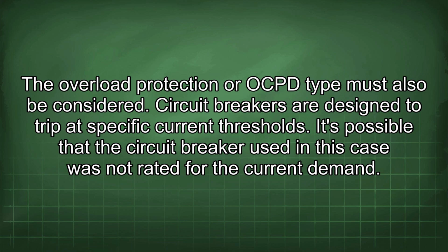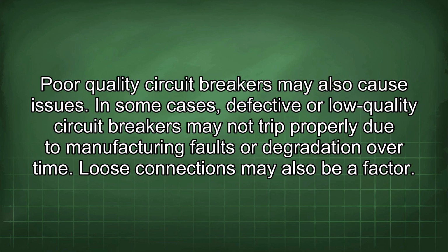Circuit breakers are designed to trip at specific current thresholds. It's possible that the circuit breaker used in this case was not rated for the current demand. Poor quality circuit breakers may also cause issues. In some cases, defective or low-quality circuit breakers may not trip properly due to manufacturing faults or degradation over time.